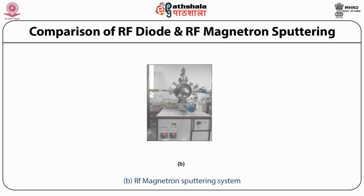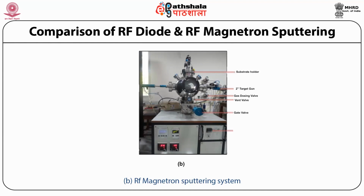The given figure here shows the RF magnetron sputtering system in which we can see a substrate holder, then the two 2-inch target guns, gas dosing valve, vent valve, gate valve, matching network. Then there is a turbo pump controller, pressure gauge display, the gas MFCs, that is argon and oxygen MFC controllers, and again the substrate temperature controller.